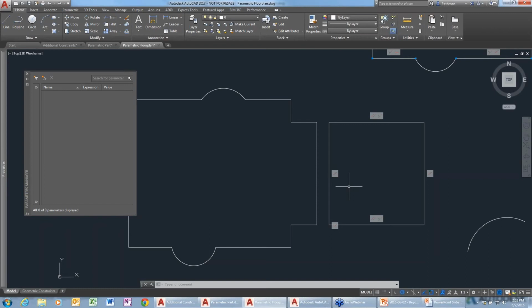This is interesting. Can you constrain nested objects, maybe XREFs or blocks, groups? I don't think so, because when I selected the 3D thing, it said select a line, polyline, arc, etc. So I don't think it'll allow you to select anything like an XREF or block. Right, so you couldn't necessarily constrain blocks in relation to each other or XREFs in relation to blocks or other entities in the drawing. Yeah, not that I can think of a way to do that now.